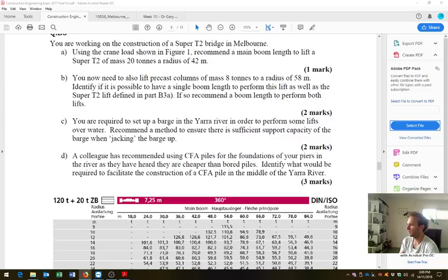A10 2015 mock, why can deep well dewatering not be used for sandy material? I got this heaps. This probably wasn't a very good question. You can use deep well dewatering for sandy material. It's just a PVC spear method is better.